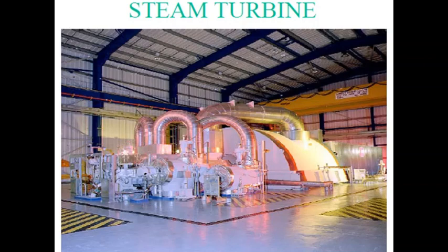These turbines, as the name suggests, handle steam at different pressures, and the HP turbine itself is the highest pressure steam turbine. From the HP turbine, for bigger units, the exhaust is used for resuperheating or reheating. After reheating, steam is introduced to the intermediate pressure turbine.